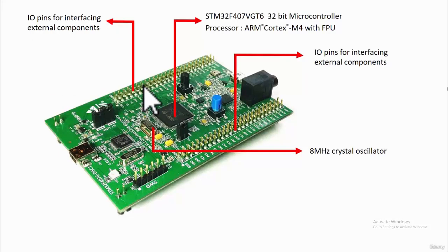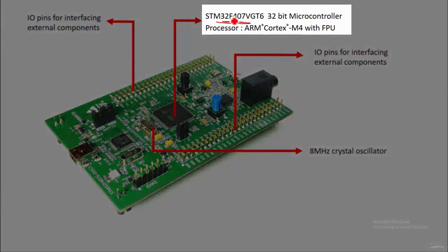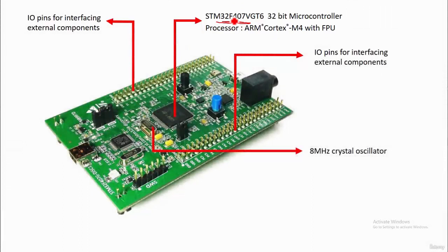The heart of this board is actually the microcontroller, which is produced by ST Microelectronics. The exact part number of the microcontroller is this one, STM32F407BGT6. It's a 32-bit microcontroller, and it is based on the ARM Cortex M4 processor with floating point unit. So this is a microcontroller.